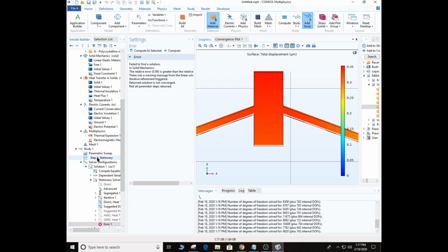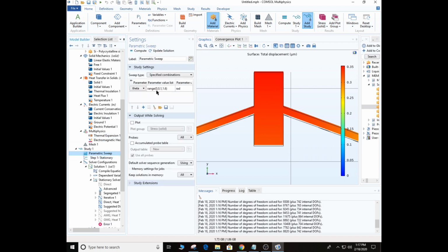I think for the sweep, you have to put degrees or change that. Yeah, if you just put... Oh yeah, it is in radians. Look at that. Thanks for pointing that out. That's very important. Well, I put degrees everywhere. I didn't even look at the unit; we'll put like 2 here. Yes, being very observant.